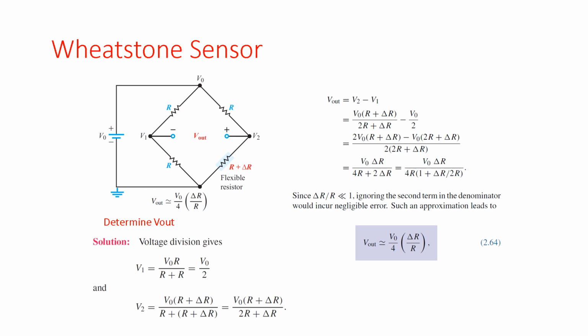Current wants to flow in the direction of less resistance, but if the resistances are the exact same, it's going to flow equally through all of them. So essentially, you're going to have the same amount of current flowing through all the resistors and the same voltage drop through all the resistors. So that's for a perfectly evenly balanced case, when all four R's are equal.